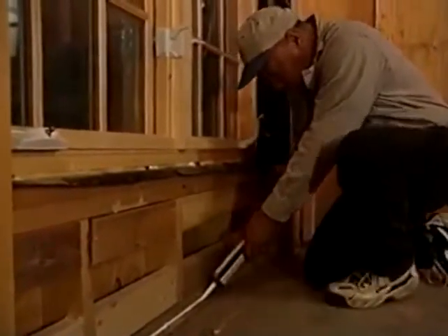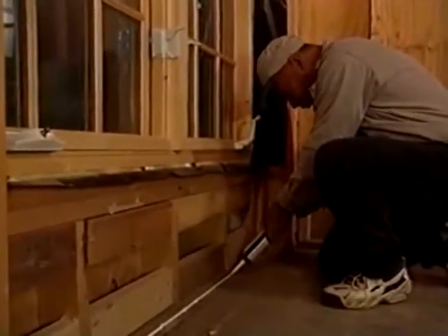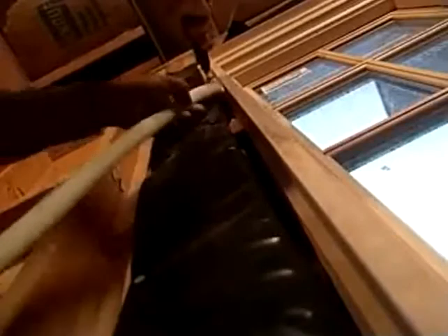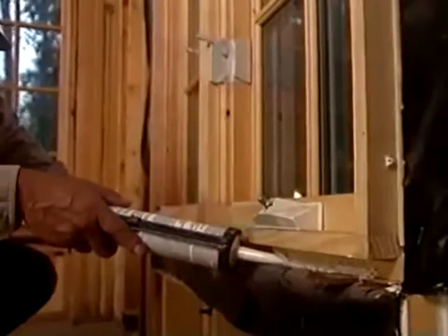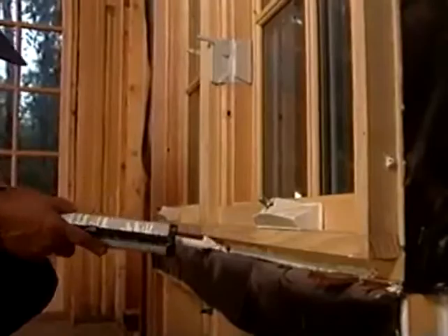Luis Ramos is a trained air sealer and insulator with nearly a decade of experience. When sealing around windows and doors, Luis uses a closed-cell foam roping in between the window and the framing. Stuffing fiberglass in this gap will not work because fiberglass is not an air barrier. He also caulks wherever he has cut the roping to make sure the gap is completely sealed. It's also important to seal any holes left by plumbing and electrical penetrations.